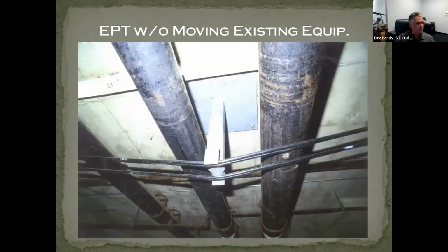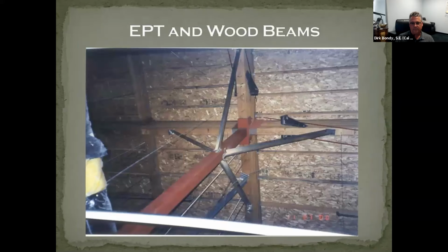One interesting thing, and there are many interesting things, is that not only are we a weightless system that's providing plenty of strength, but you can actually thread this through the existing mechanical, electrical, plumbing system. Most strengthening systems have to remove all of the other systems in the building, the duct work, the piping. That all has to come down so that the strengthening can go in, and then all that goes back in afterwards. We've actually been successful at just putting the external post-tensioning in and diverting around the existing systems. Again, creativity is what this is about.